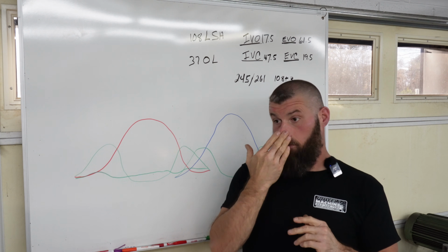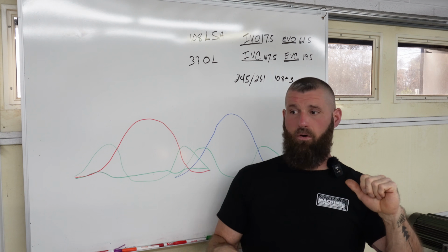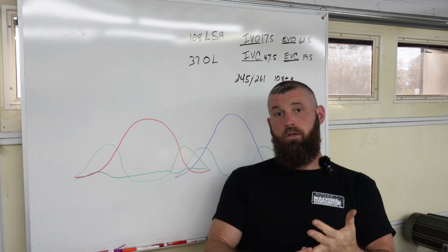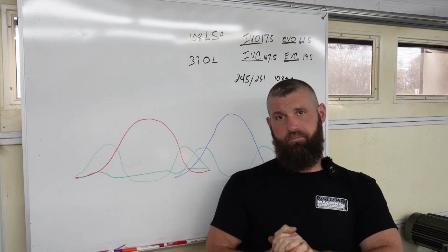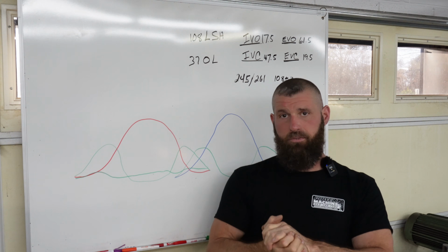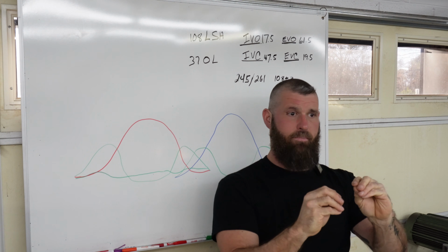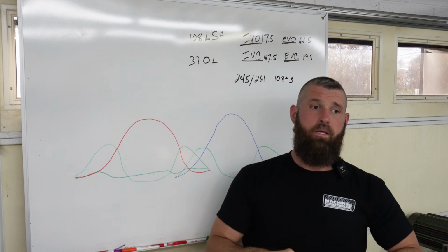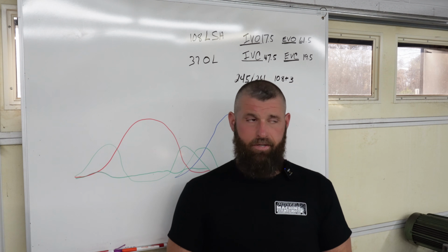So whether you get, I'm spitballing, a 220 at 50 or a 245 at 50, if the number is 53 on hydraulic intensity, both lobes will have a 53 hydraulic intensity. Both lobes will have the same positive acceleration, and they'll both have the same velocity and acceleration at the pickup point, right? And so that is the goal, to have uniformity in a family.